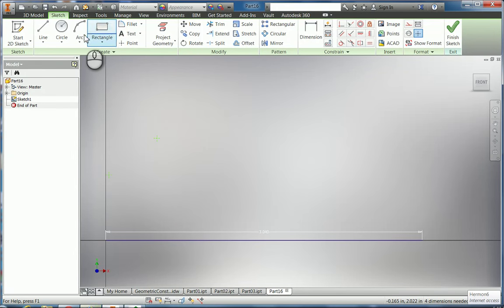Okay, so now I can make some arcs. I'm going to make what's called a 3-point arc. If I click on this, you'll see it's 3-point arc, which is kind of deceiving because you click on the first point, which is down here. Click on the second point. We're bending it, so it's going to be bent out a little bit, and then what you're putting in is basically your radius to your center point, which is a 6. Hit Tab, and then hit Return, and so now I've got an arc in there.